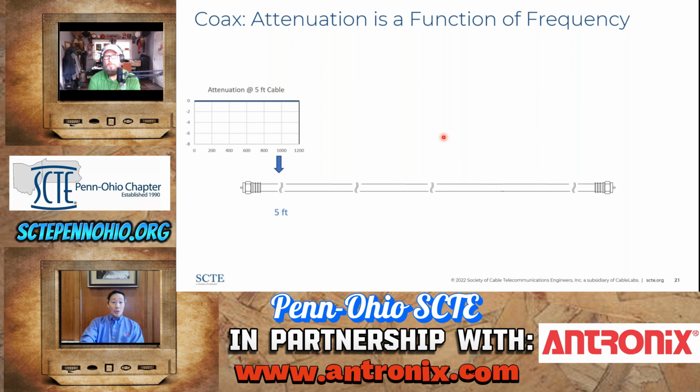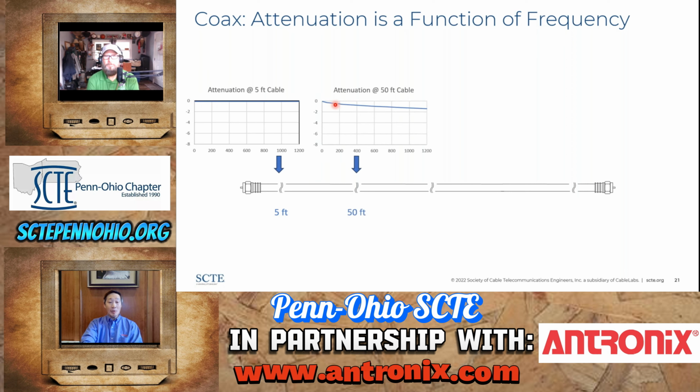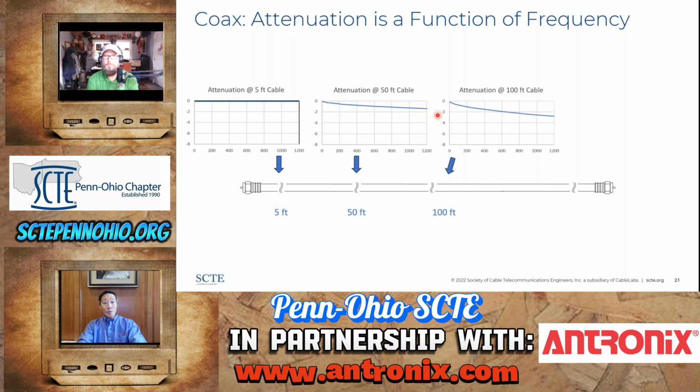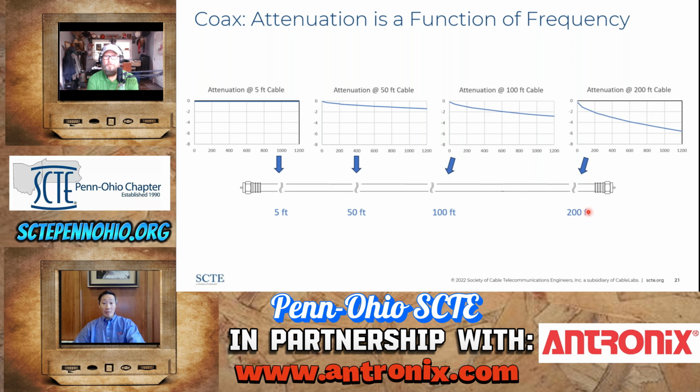So if you have a very short piece of cable, let's say 5 feet, you're getting pretty much a straight line, very little attenuation. But as the length of the cable increases, if you measure the frequency response at, let's say, 50 feet, you can see there's starting to be a little down tilt to this. And this will be more pronounced as the length of the cable gets longer and longer.